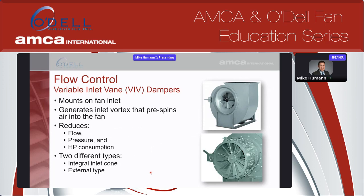They both generate a vortex that pre-spins air into the fan, and that actually detunes the fan. It reduces flow, pressure, and your horsepower consumption. These can be really good to throttle back a fan if you don't need the full capacity out of it, and also to help change the curve shape. We'll show a little bit more about that in a second.